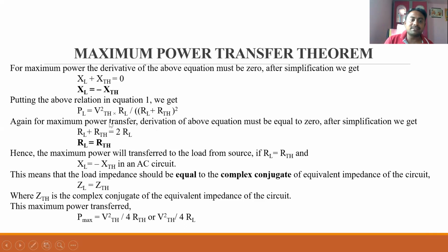So in both cases, we differentiate the power equation with respect to reactance and with respect to resistance, and we get two different conditions. For the real part, the load resistance equals the source resistance, and in the case of reactance, the load reactance equals minus the source reactance.